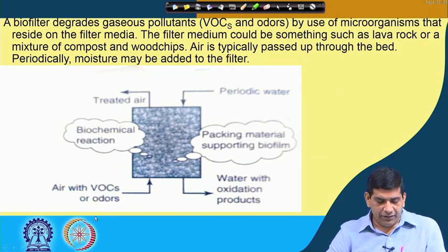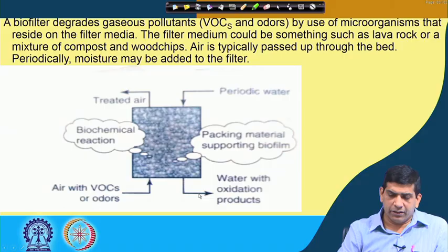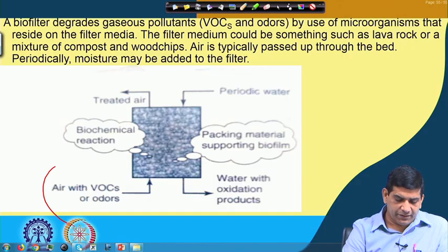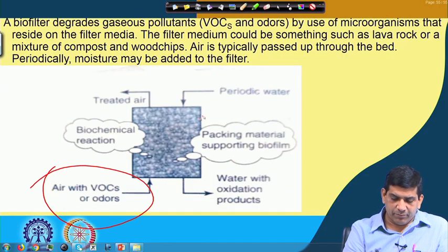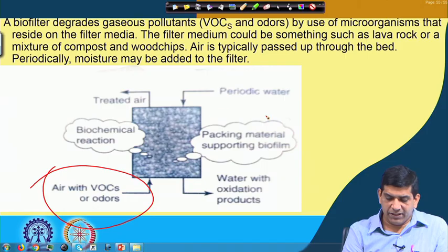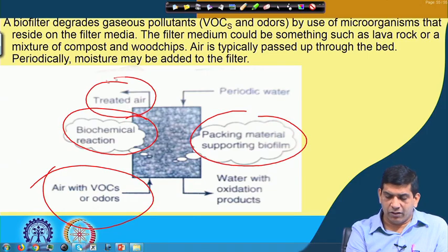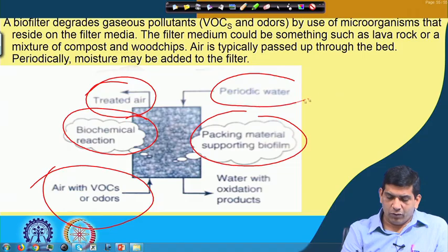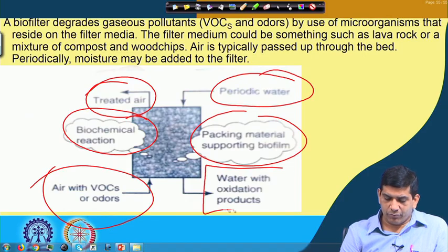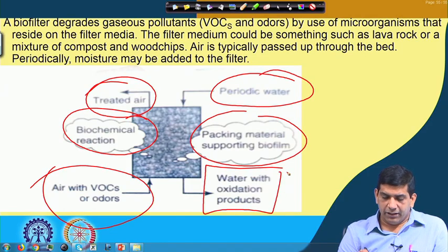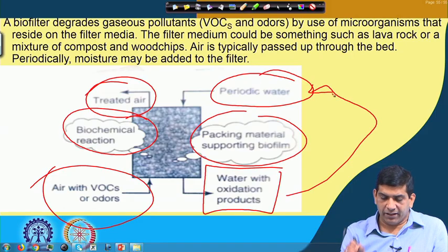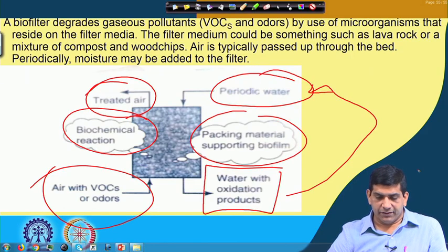So, you have air with VOCs and odor getting in there. Here we have biochemical reactions: the packing bed supports the biofilm, the biochemical reaction takes place, and the treated air goes out. We add periodic water, and the water with oxidation products is also taken out, so that you can treat this water and recycle it back as well.